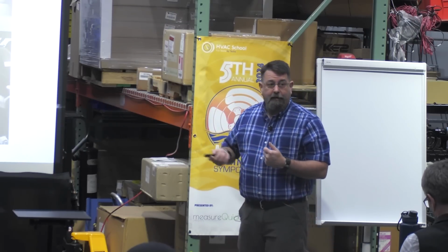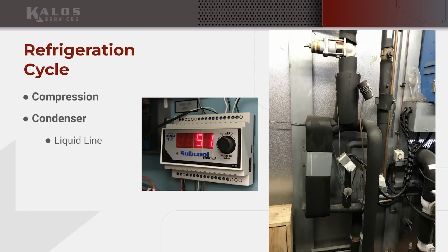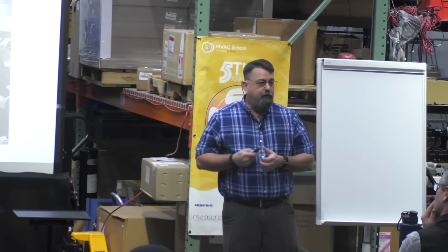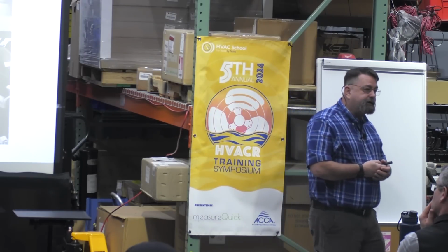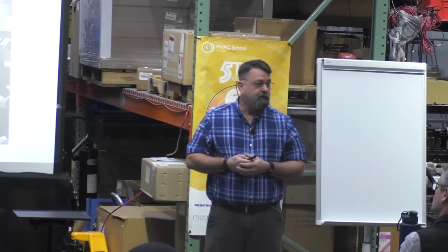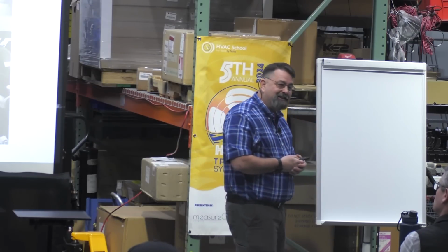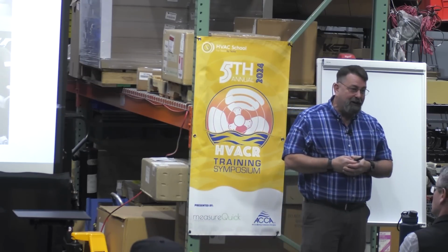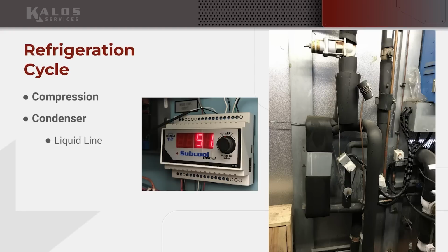To do that means I'm going to really subcool it, all right? And if you notice, my liquid lines are insulated. There's something you don't see. Why is that? Well, because I've done all this work with a mechanical subcooler. That's what this is. I'm going to bring that liquid maybe down to 50 degrees, right? Some CO2 stores I've seen 20, 30 degree liquid, right, below freezing, right? That's some subcooling. We're getting some extreme subcooling, all right? So how are we doing that? This might be new to you, don't know, depending on your background.